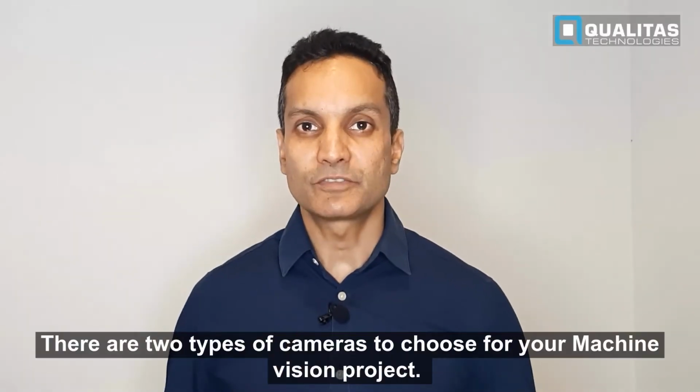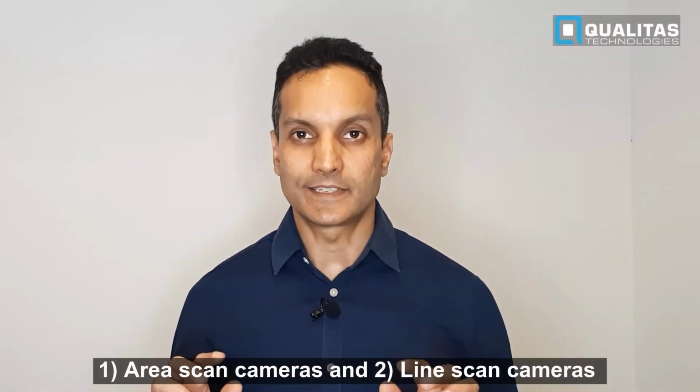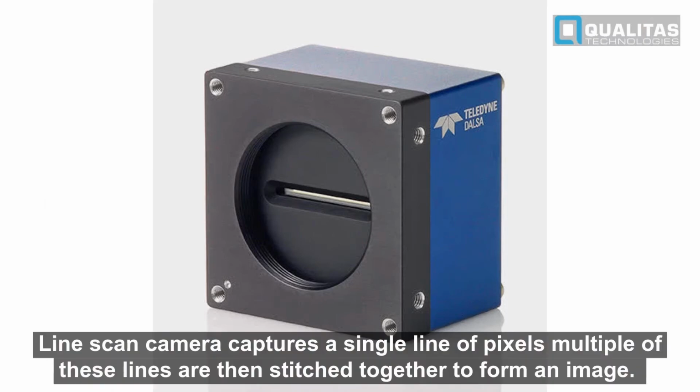There are two types of cameras to choose for your machine vision project: area scan cameras and line scan cameras. Area scan cameras, as the name suggests, capture an area of pixels in one frame of your image. Line scan cameras capture a single line of pixels. Multiple of these lines are then stitched together to form an image.